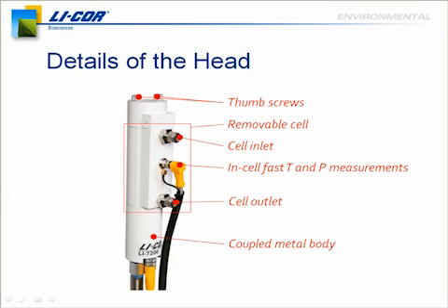The instrument's also mechanically designed to not trap any debris. There are no sharp corners or pockets where debris can accumulate, especially on the windows. Surprisingly, we don't even need to have a filter for this analyzer. We do provide a bug screen, which keeps large bugs from getting sucked into the system. And there's also a rain shield for those that want to avoid getting rain sucked into the analyzer. But filters, like those typically used, like the Gelman filters, aren't needed.